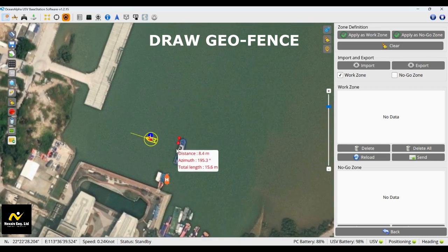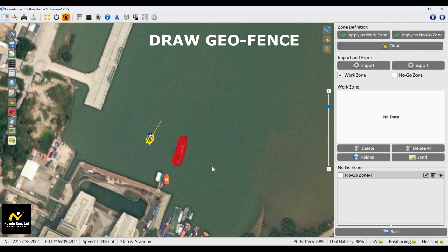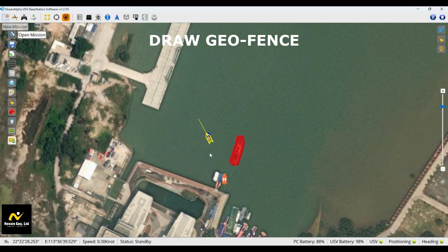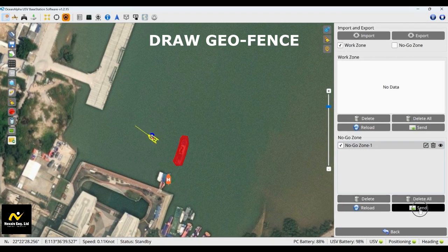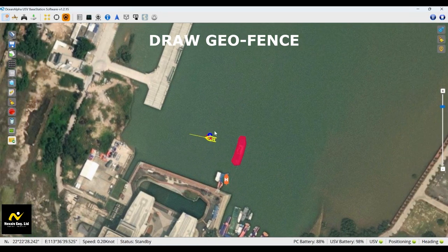When an area is geofenced, by either digitizing or extraction from a map, you should normally select the area of interest to be geofenced, and then you apply the settings, and this in turn highlights that area so that in the event of a data capture, the USV is able to go around or completely avoid the area that has been geofenced from the mission data capture.